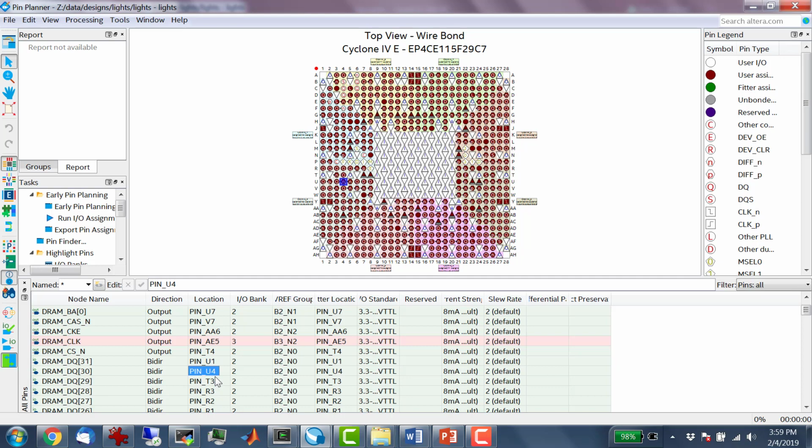You might say, well, how do I use them for stuff? Well, you can't, because by user, I mean whoever's making the PCB. In other words, in order to connect one of these pins to something physical, you would have to do that when you manufactured the printed circuit board that you put the FPGA on. This company that we bought these from already made it, so there are predefined connections between the pins and specific components on the board, which are defined in the pin mapping file. Once you import that pin mapping file, you should see the pin mappings in the pin planner.